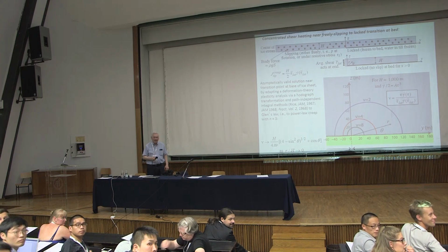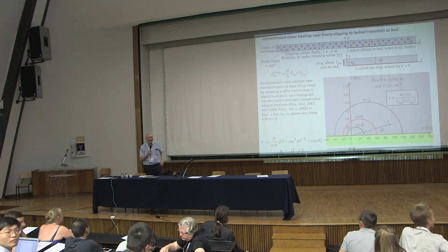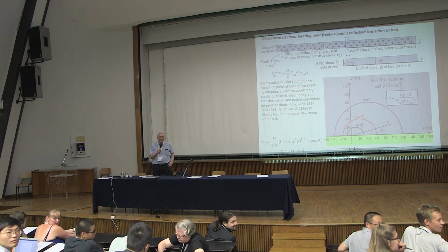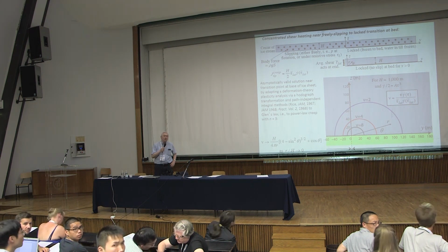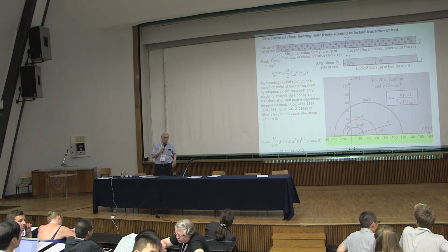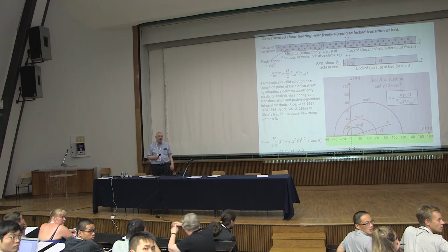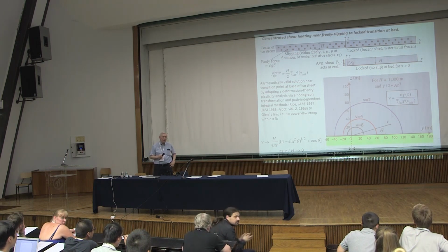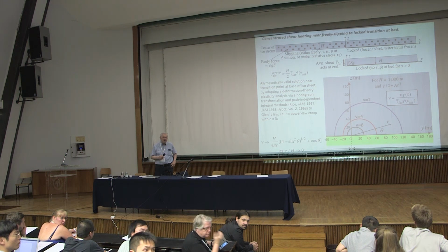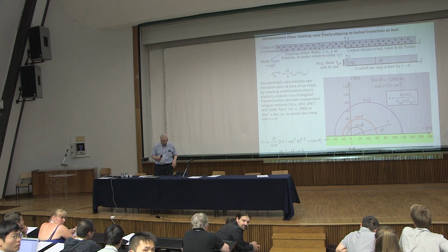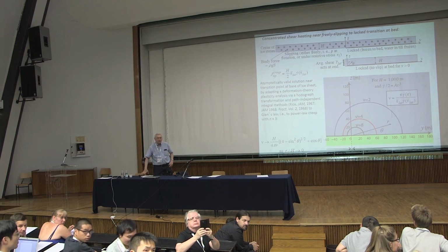John, any comment on direct measurement of J integral? Done by Dave Reed and people from NIST, using a single load displacement curve to estimate J. I think he put strain gauges around a loop and measured a path integral. Oh, that's a different technique. Yes, I think he did that, and of course, the energy rate definition is what got Jim Bailey and me going for that. It seemed like a direct way using energy rate, but he wanted to do the path integral, so he did measure that, and it seemed to work.